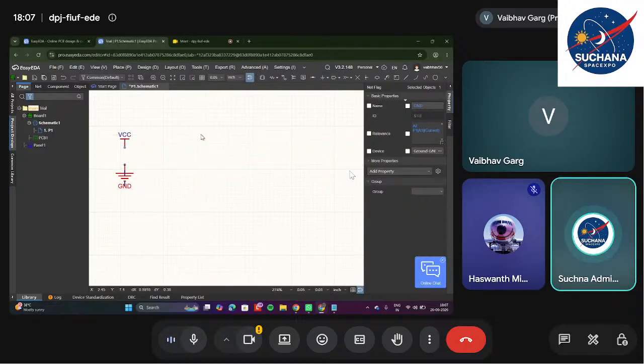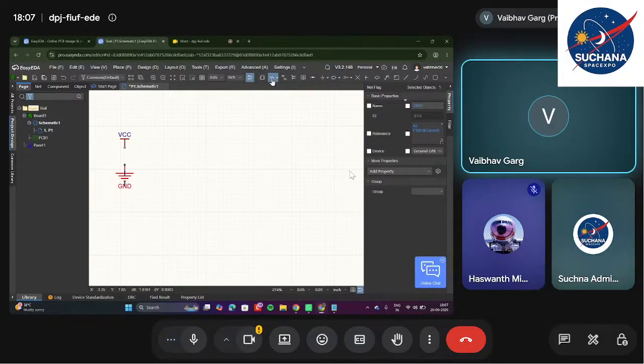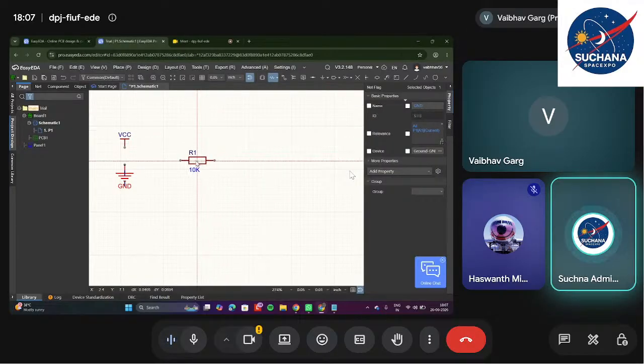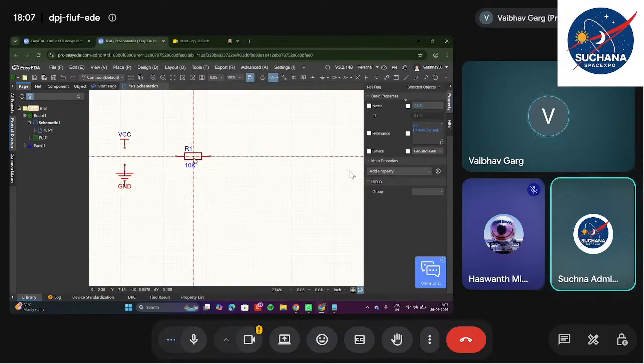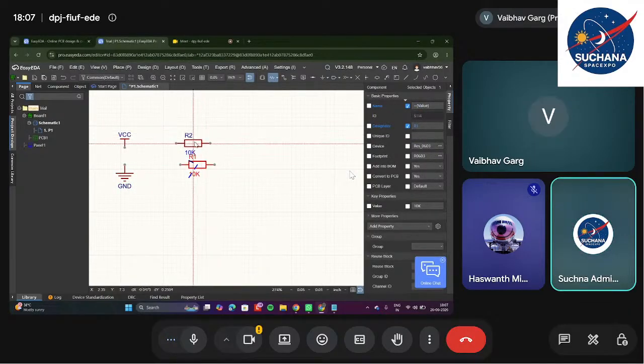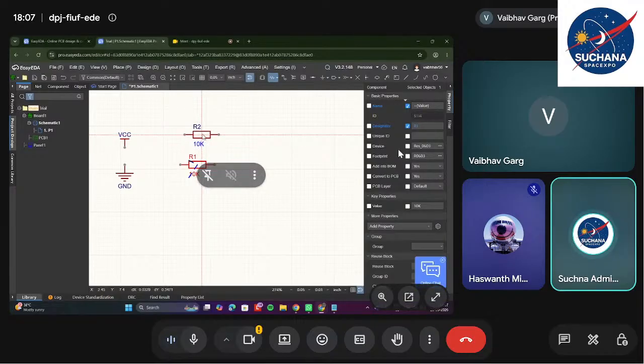Can you just identify that? Just the right one. Click on that. That's the resistor. See, the designator came automatically. Now place one more resistor, and automatically the value will be incremented. Instead of R1, you will get R2 next. Place that second one and click on escape.